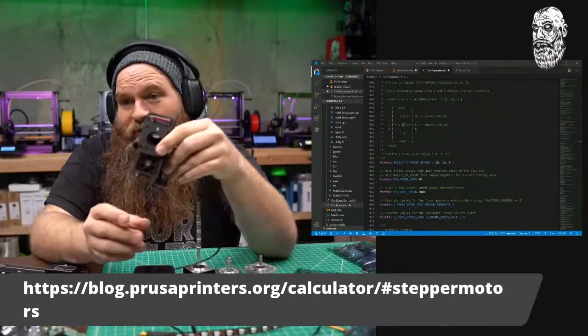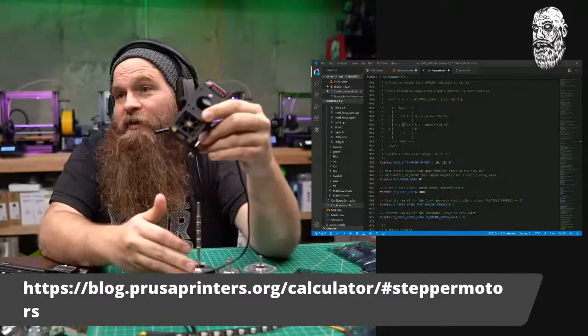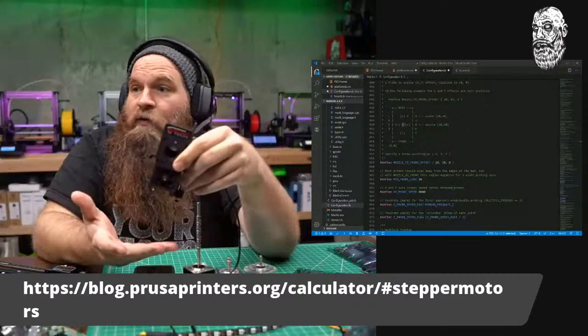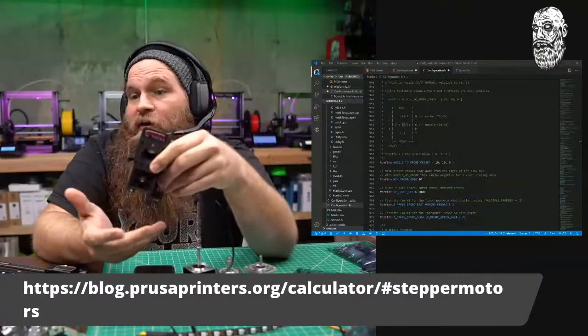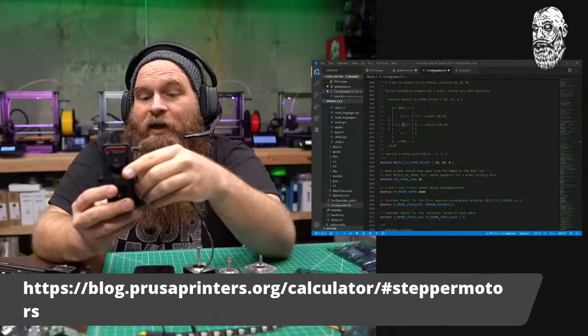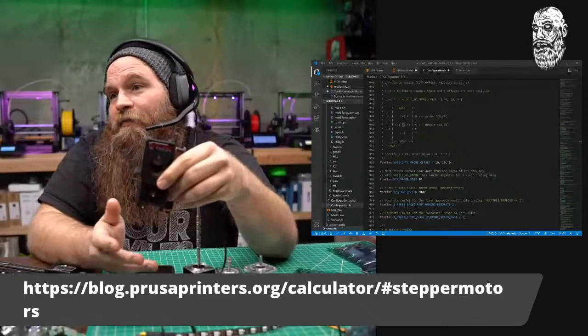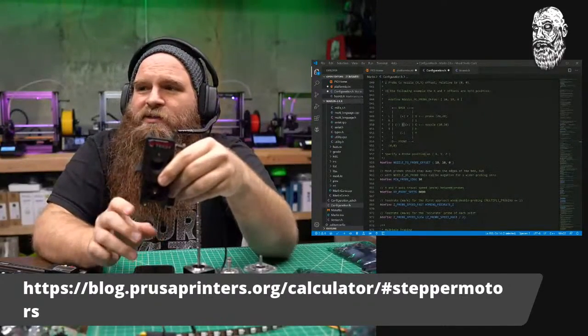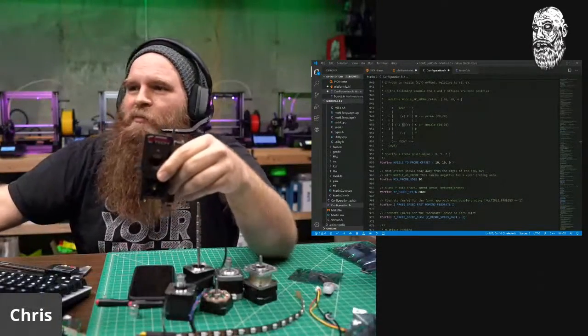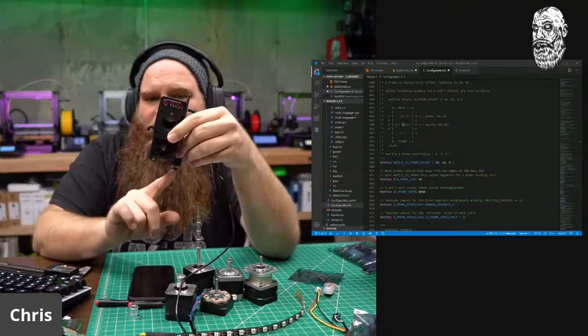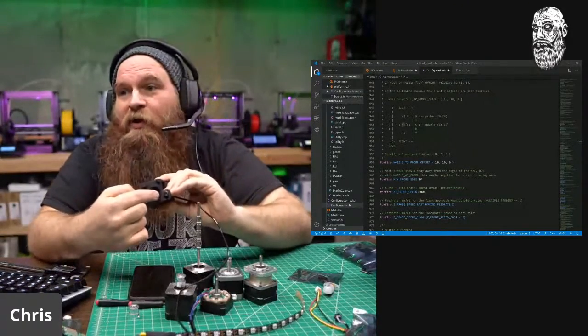Michael, which one? Pinda? I prefer the BL touch, but I have no qualms on using a Pinda or anything similar. They all work. I'll get into differences on probes later, but for now, we need to know basically where in space the probe is compared to where the hot end is.